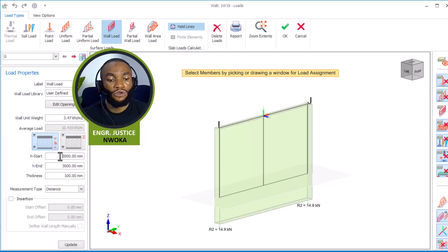So with this now, we have to input the height that we did. We had 3375. Okay, that's what we had. Then I come and put in the width, the block wall thickness, which is 225. Okay, that's fine.